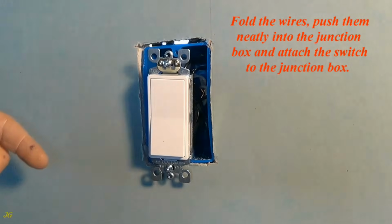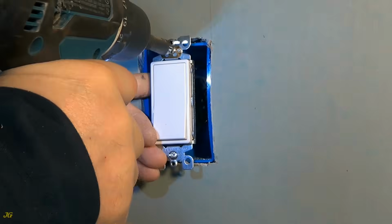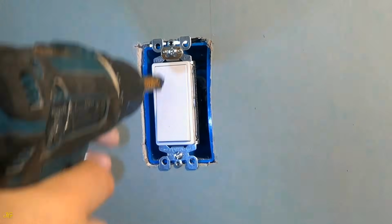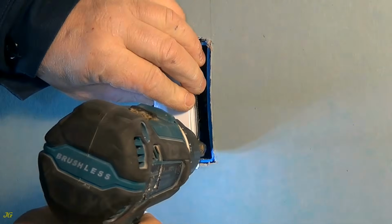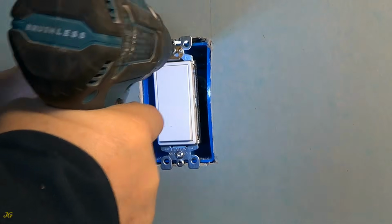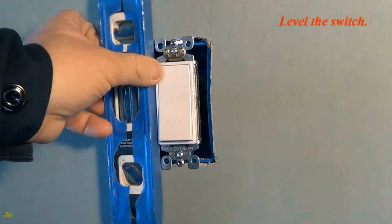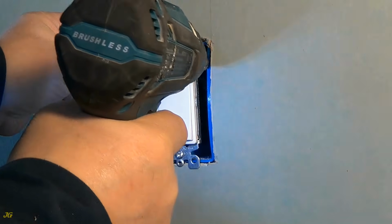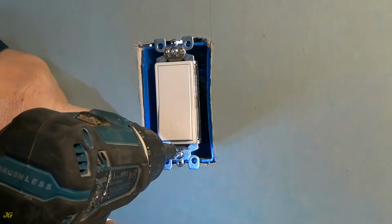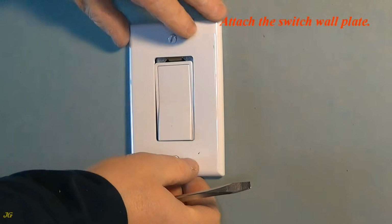Push them neatly into the junction box and attach the switch to the junction box. Level the switch. Attach the switch wall plate.